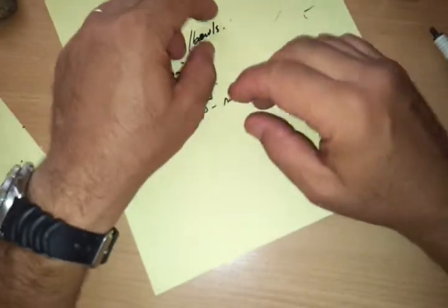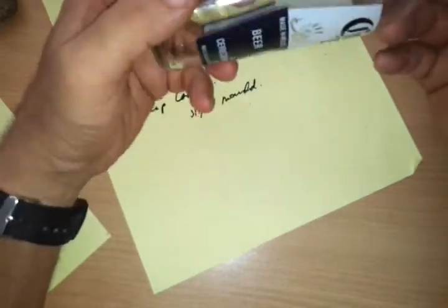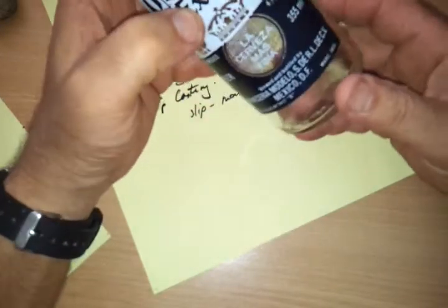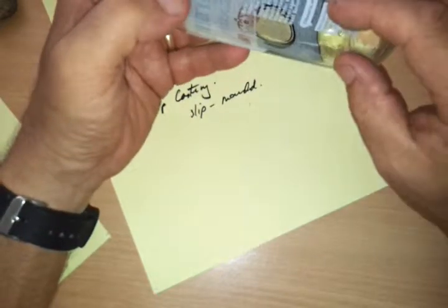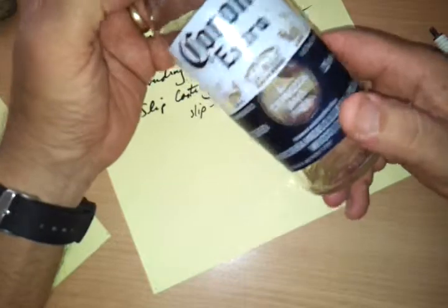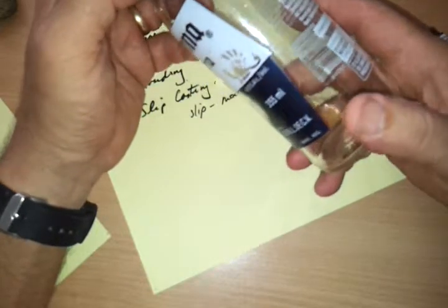Now glasses are a bit of a slightly different item. They're defined as a fusion of inorganic materials that have been cooled to a solid without recrystallizing. So I'll say that again: it's a fusion of inorganic, so not organic, materials that have been cooled to a solid without recrystallization. Typically when things are cooled to solid, like metals for example, they crystallize. Not so with glasses, and they are a ceramic.